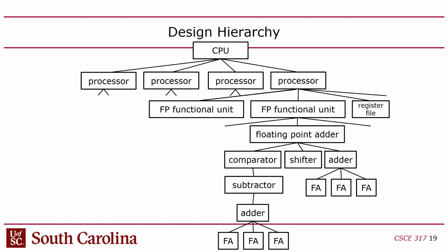The problem is that the design hierarchy is fake. It's all made up, because when it's put into hardware, the hierarchy is flattened into a big mass of wires and transistors, right? So this whole design hierarchy is only there in your design. Once you deploy it in hardware, it disappears. So what ends up happening is that if you have a signal with one name in this module that's connected to another signal in this module with another name, it's the same signal, it's the same wire, two different names. But when you look at the design on the FPGA, which we're going to do in this class because we're going to put probes in the FPGA to test things, you don't know which name to look for, because all the names get deleted except for one.